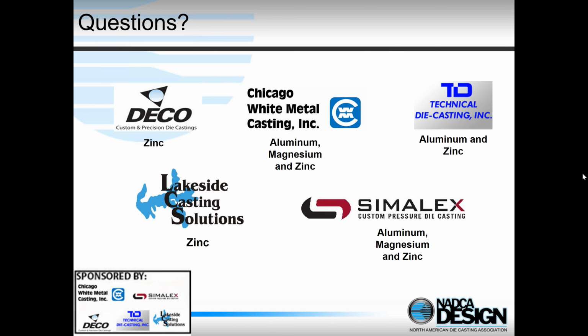Again, as we talked about at the beginning, I see there's one technical question anyway: what is considered premature failure, how many cycles? Well, clearly it's dependent upon the alloy being cast. Zinc is the lowest melting temperature. Basically, the die normally fails from heat checking, which is this thermal fatigue.